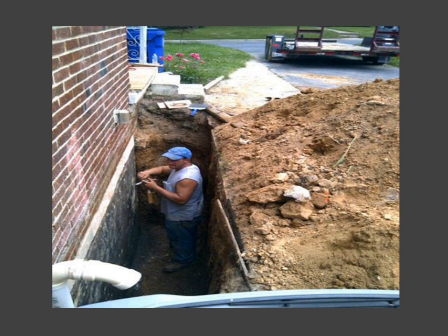It's not tiered, so therefore it must be supported. And he can support it either by putting in a plank wall, or he could put in a trench box. Either one could go in there and he could do a safe operation. Doing it the way he's doing it is an accident waiting to happen. And obviously nobody thought about it, or maybe even worse, cared about it.